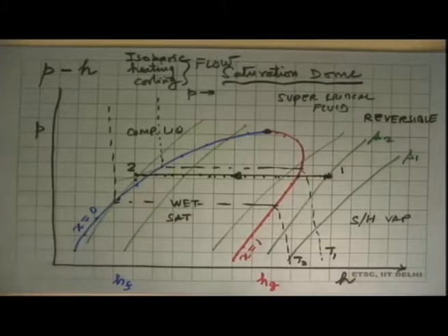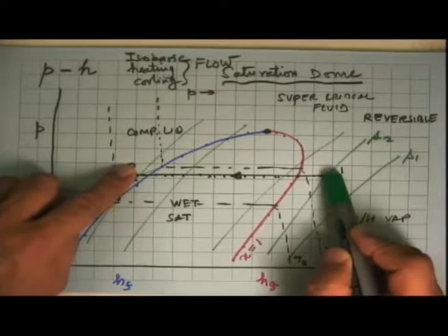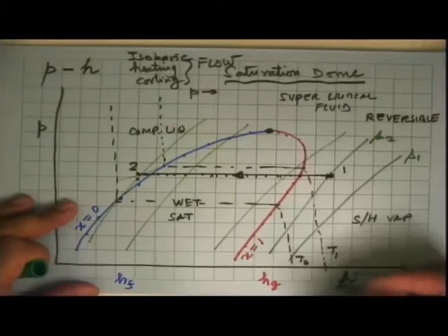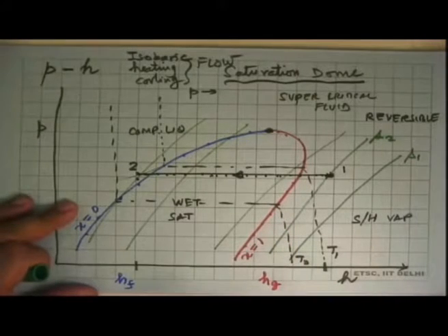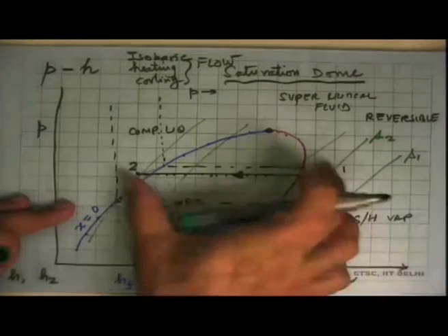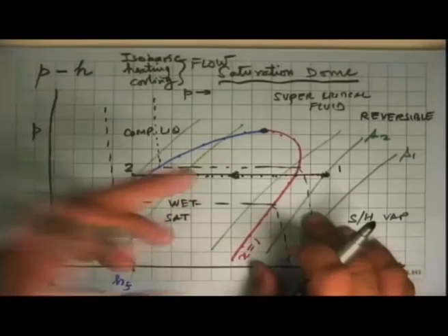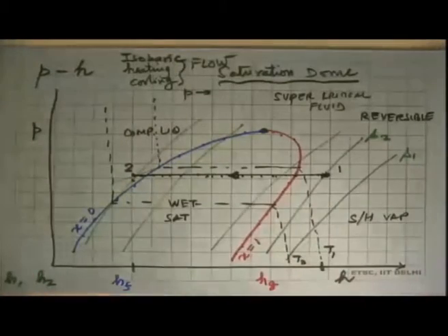Well, if you do the mass conservation and first law analysis, you'll get a relation that heat transfer rate is the mass flow rate multiplied by the enthalpy difference between the inlet and the exit states. That is quite nice because you can just go down this chart, look up this value of the specific enthalpy, go down this point, look up this value of the specific enthalpy. We can get h1, we can get h2, and the difference of this is the enthalpy drop during the process. That multiplied by the mass flow rate is the heat transfer in this process in steady state, no change in kinetic and potential assumptions. That's a nice thing to know.